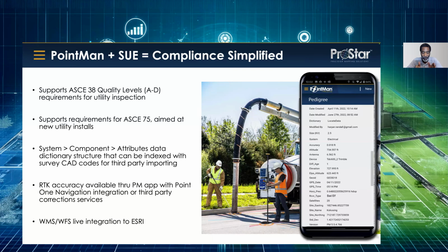And again, have it in a KML file, KMZ file. You can ship it to someone in the office and they can download that data. KMZs and KMLs are very easy to import into Map 3D, which is an Autodesk product, or Civil 3D. And then you can actually utilize that data. But what's also interesting is that if you have data that is in Map 3D or Civil 3D, you can convert that data into a KML file. And again, centimeter accurate, go back out and actually put paint back on the ground, showing the exact location.